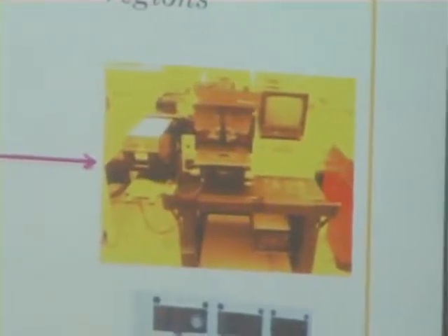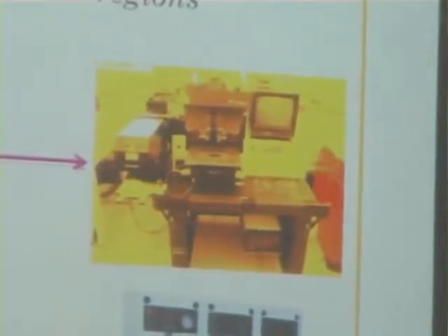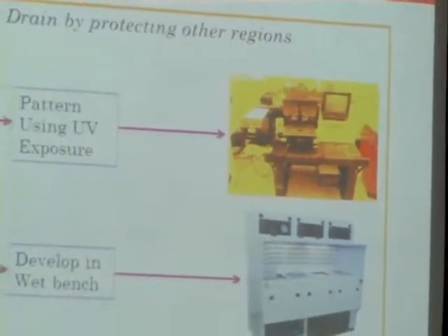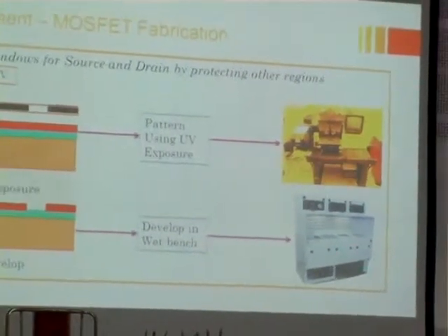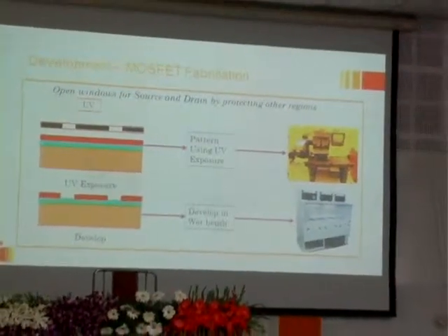There is a special component involved wherein you get nanometer dimensions as well. There is this nano imprint lithography equipment that we have purchased, which can fabricate nanometer dimensions. After that, if I expose it and want to develop it, we need a wet bench, wherein you have to have ultra pure chemicals and do wet chemical processing.